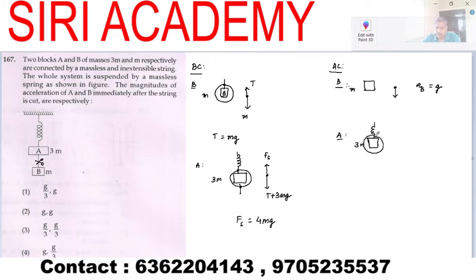So I can say that Fs minus 3mg is equal to 3m into acceleration of A. So acceleration of A is equal to mg by 3m, that is nothing but g by 3, and it is in the upward direction, and for B it is downward direction. So the option corresponding to it will be g by 3 comma g.